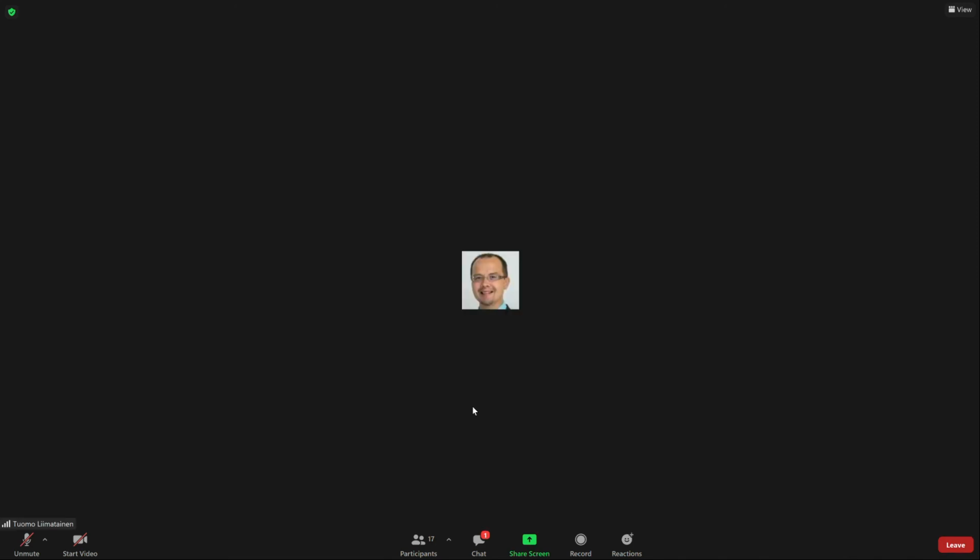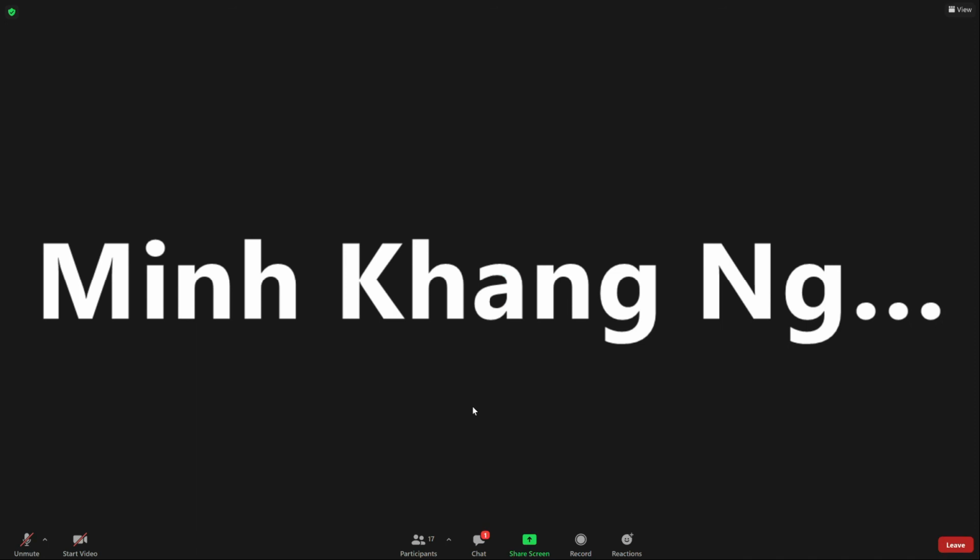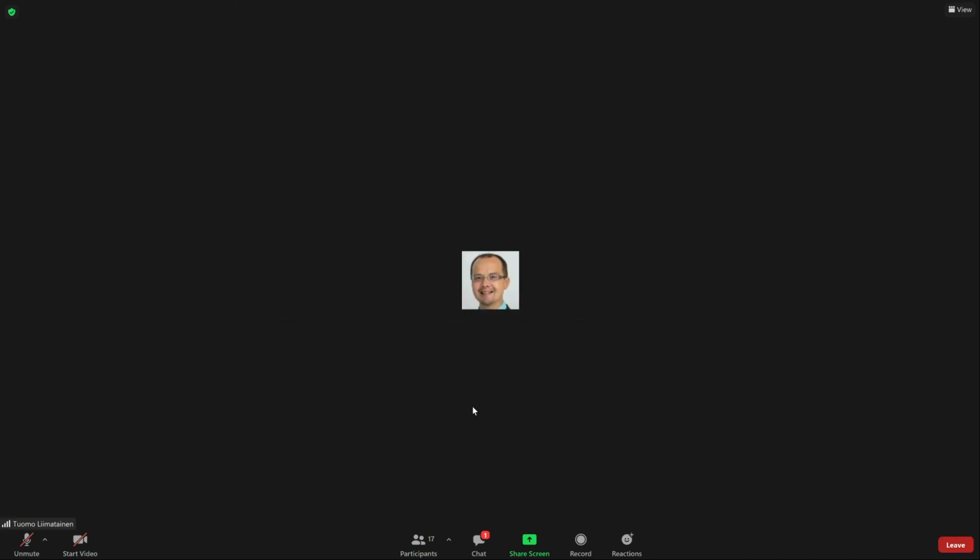If you increase D2, I think it will not help you, because then you will basically increase the notch effect. So I think you should either increase D1 or increase the radius between D1 and D2. If I increase D1, the safety factor is over 2, so it does not meet the requirement of the task. Well, can you select D1 so that you would be exactly at 2 in the static analysis?